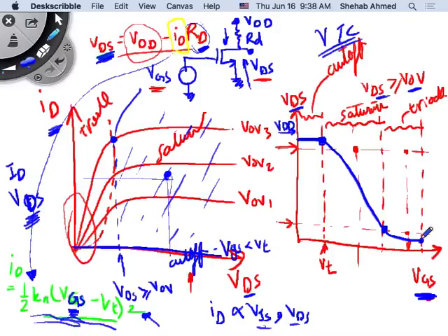Okay, so this is the corresponding curve. We're okay with this? From here, it's easier to analyze a small signal. Why? Because I'm creating a voltage amplifier. My input is a voltage, and my output is a voltage. Right? So this is nice, this is useful, but this is more useful for analyzing small signal. And this comes from this. They're the same. I just substituted with the equation for current to come up with this curve.